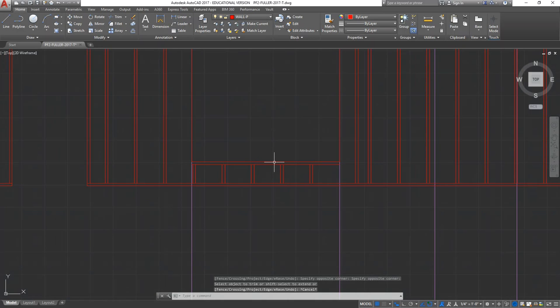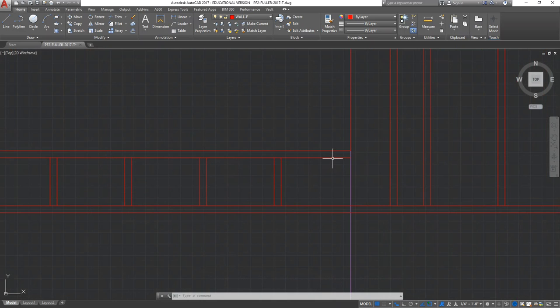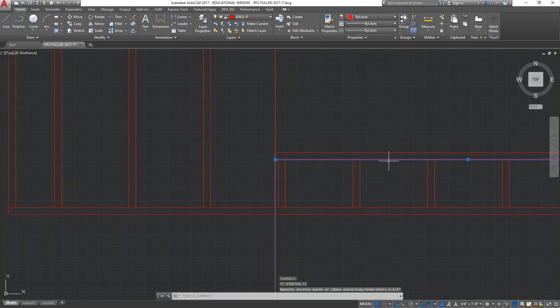Now I'm going to take my trimmer, and it's going to extend an additional 1.5 inches, just like the header did. I called this a trimmer just now, but I realize that it's not. It's a window seal. Okay, pull to the right, 1-1/2 inches, and that didn't work. Let me try it again. 1-1/2 inches. That's probably why. And extend this one. Drag to the left, 1-1/2 inches. Okay, so that's extended 1.5 inches to either side.